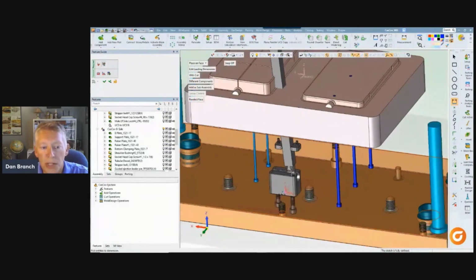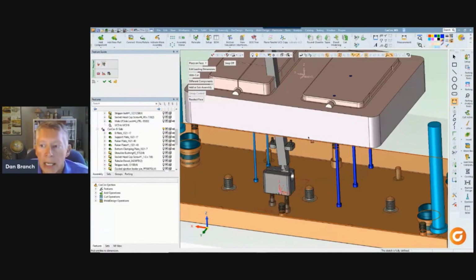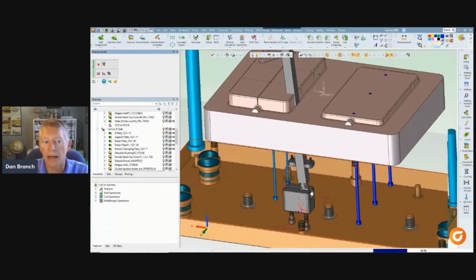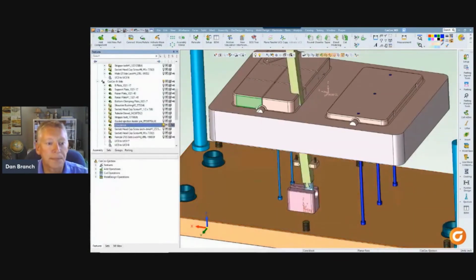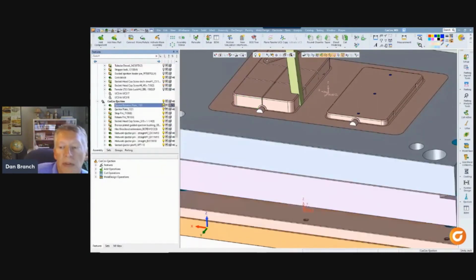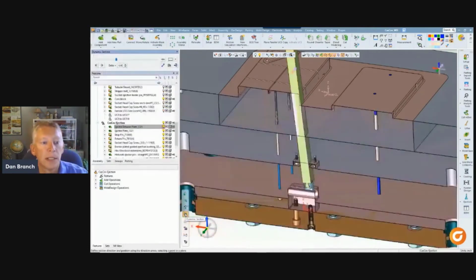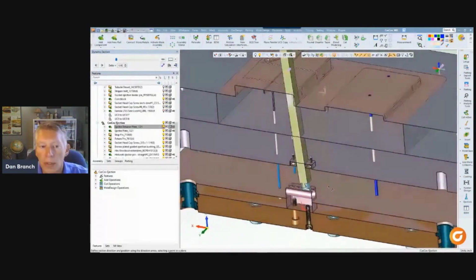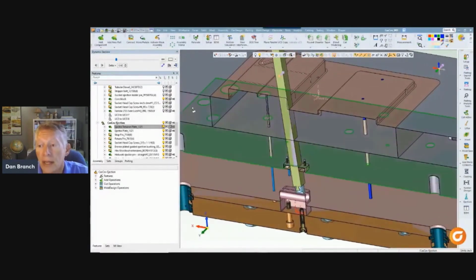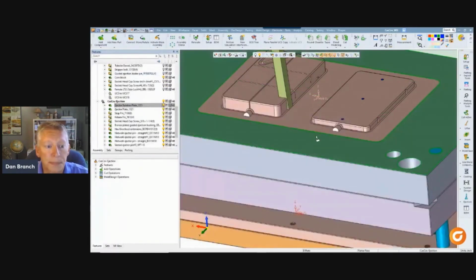So all of that adjusting probably means repositioning the lifter a little bit, which is as simple as changing the dimension, of course. And then I do want the cut option on for sure. So I get all the tapped holes and pockets for all these parts that we're adding installed. That's done. Let me just put a few more of the mold plates back on so that when we look at another quick section view, we can really see what all took place. Every pocket for every lifter component has already been correctly created in the plates. So with all of that handled automatically, I really only have one other task to do.